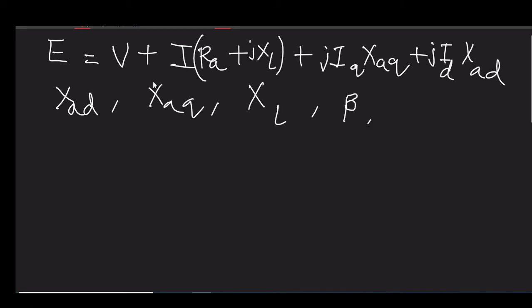In addition, we know other things we can measure like V, I and also power factor. Those are measurable from our available instruments. So these four are known to us. Then we are ready for construction of phasor diagram.